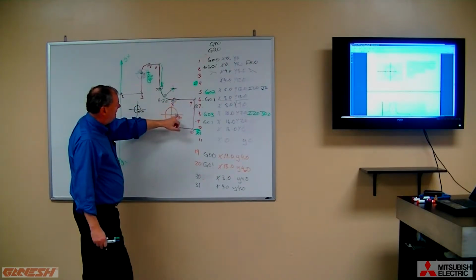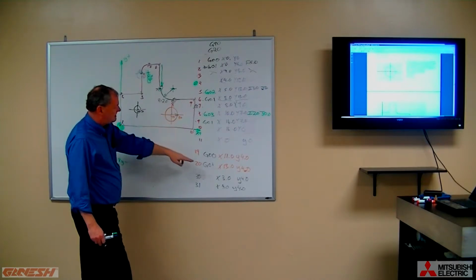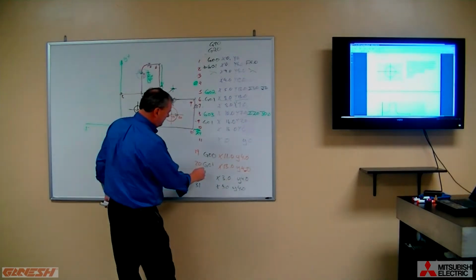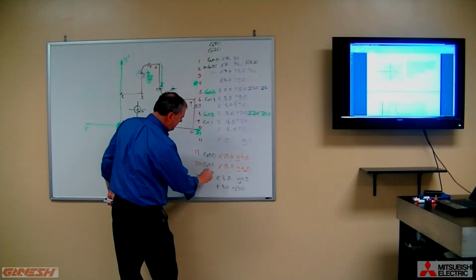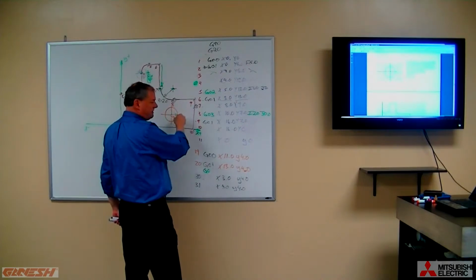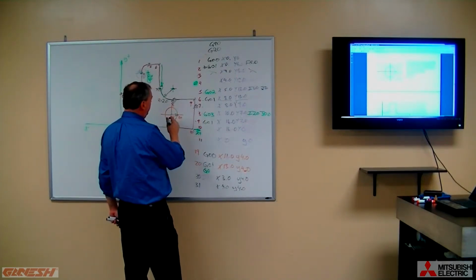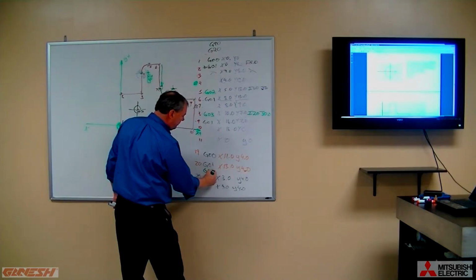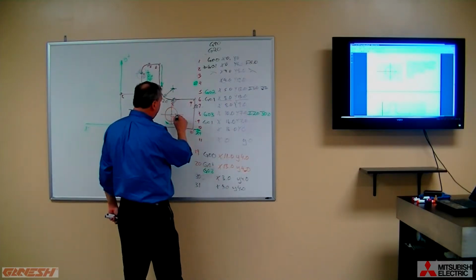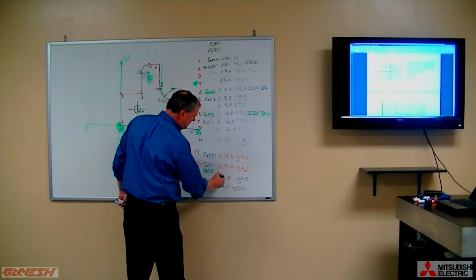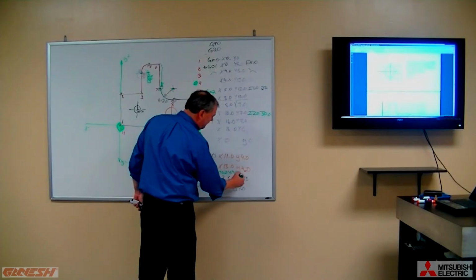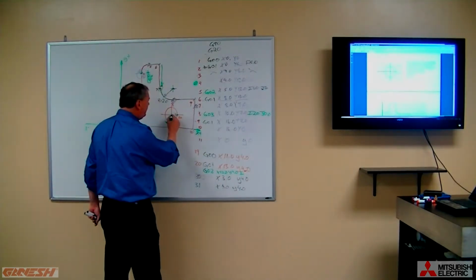Well, because we're beginning and ending when we're cutting a full circle at the same location, all we need to say at this point is G0, and now we're going to go clockwise or counterclockwise, whichever one, doesn't matter. Well, it does matter depending on the finish you want, but let's just say we're going counterclockwise, so we'll say G03, and all we're going to do is go back to the same location where we're currently sitting at, X13.0, Y4.0.